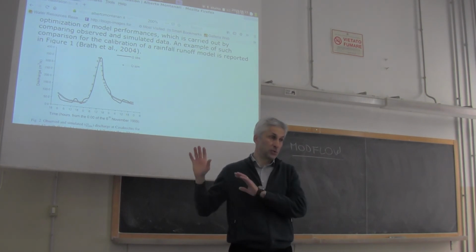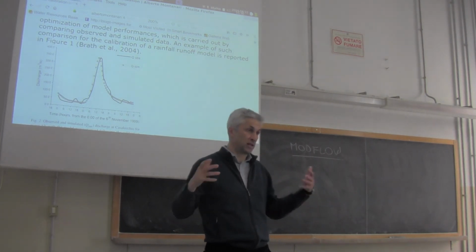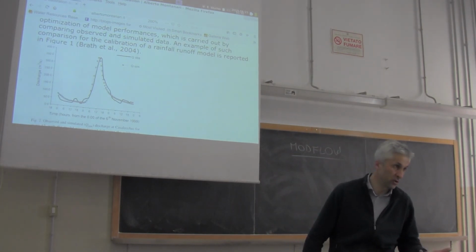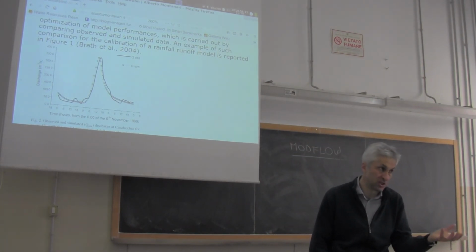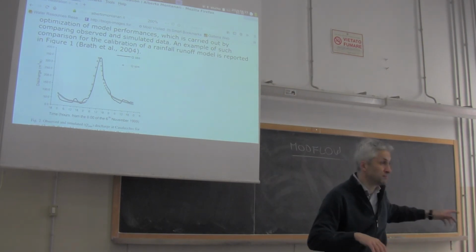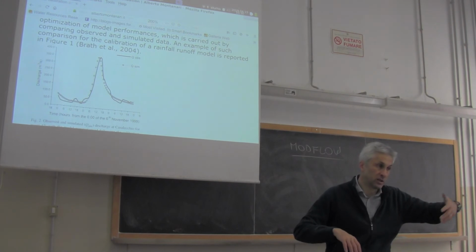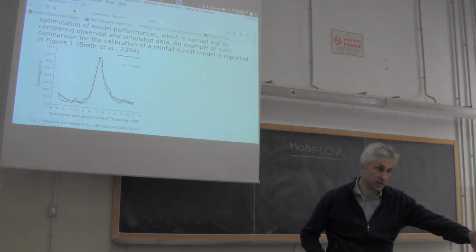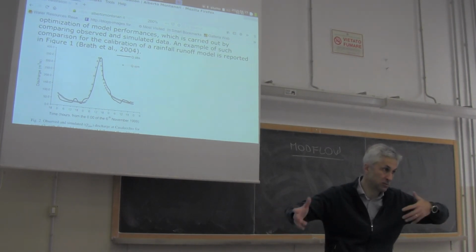The same can be done for aquifers. You have observation of water level. You have observation of rainfall, which means recharge, which means Q in an aquifer. You put rainfall into MODFLOW, and then you get simulated water levels in wells, and then you compare simulated versus observed.